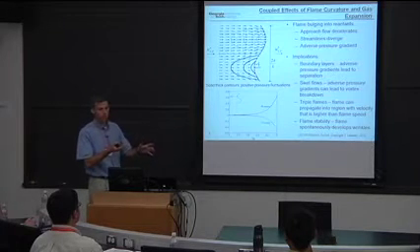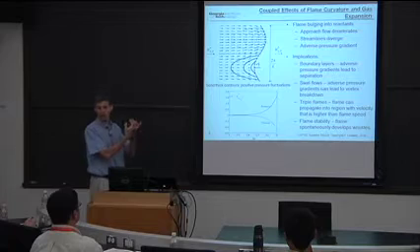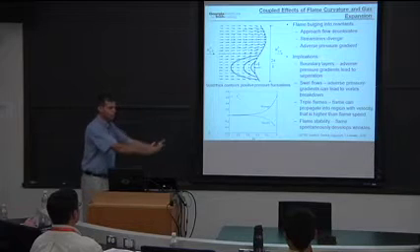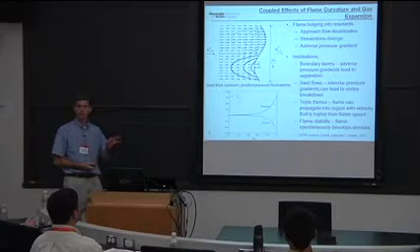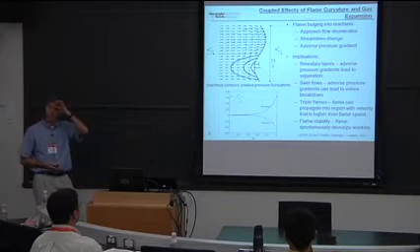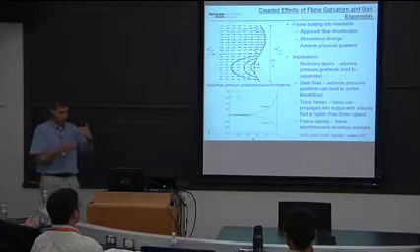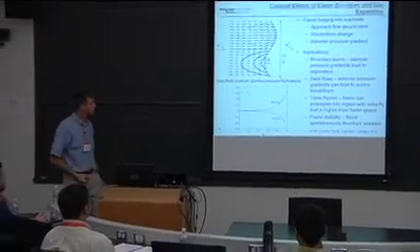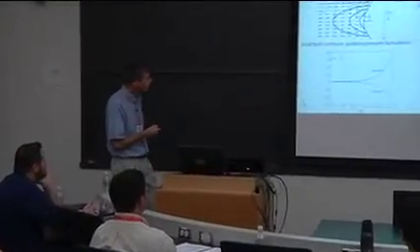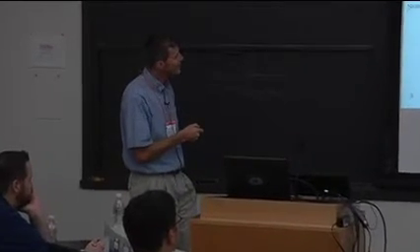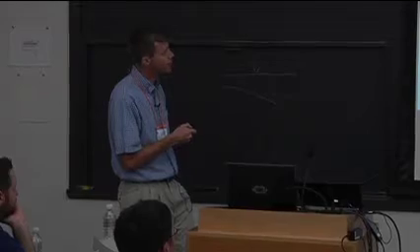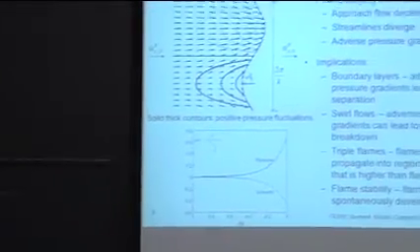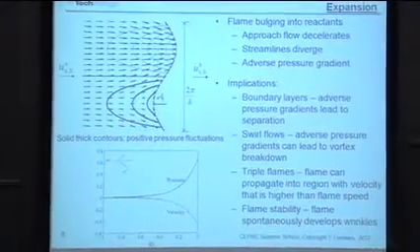What does that mean is happening to the pressure? The pressure is rising. Although globally the flame is going to impose a pressure drop on the flow, locally the flame is imposing an adverse pressure gradient on the flow. The flow is decelerating. The flame is like a back pressure. It takes extra force to shove the flow through the flame. The pressure is rising. The exact opposite thing happens on the concave part. The flow accelerates, so there's even more of a pressure drop. The pressure is already dropping even before the flow hits the flame, then it drops more through the flame.